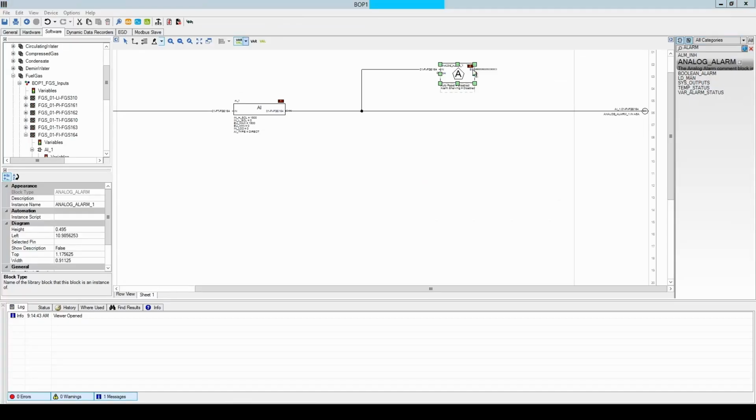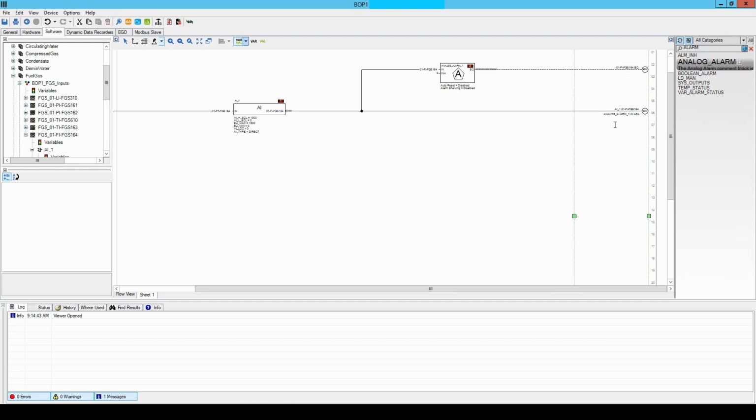And then I'm going to change this to a level 3 bad quality alarm. And that's done. And then I don't need to do this, but once again, I'm going to drag the BQ to the rail. And it'll tell me where it's used. Once again, it'll function without that. Now, here's another thing about alarm blocks. It appeared that you configure it here in the alarm block, but really you're configuring this point in the variable.